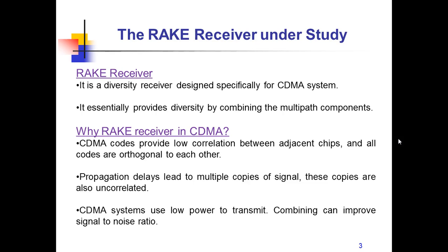That is, what is a rake receiver? A rake receiver is designed for CDMA systems. It provides diversity by using multiple matched filters. Each branch, or finger, of the receiver has a matched filter, and it can detect one multipath component. After collecting and detecting a certain number of multipath components, they can be weighted and combined to produce better decoding performance in terms of bit error rate.